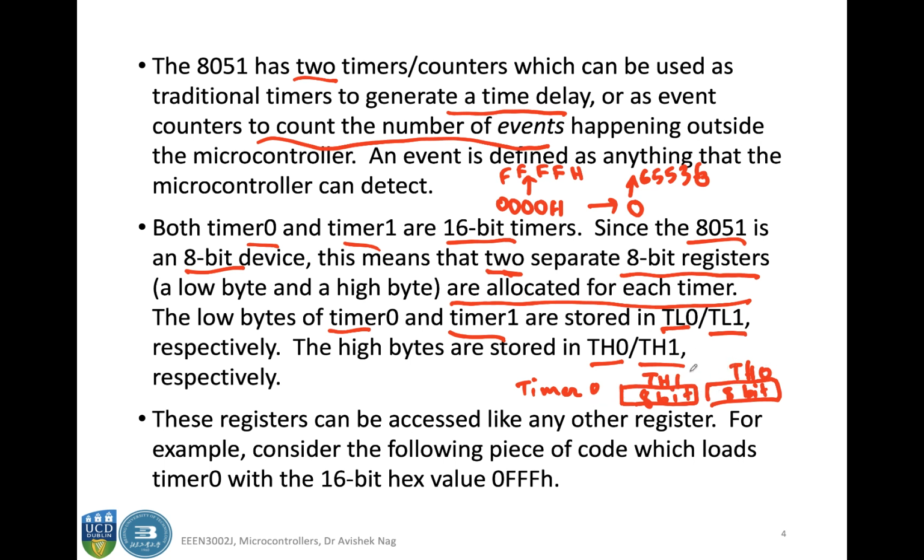Similarly for timer 1 also. So this is TH0 and this is TL0. Okay, TH0 for the high 8 bits and TL0 for the low 8 bits.